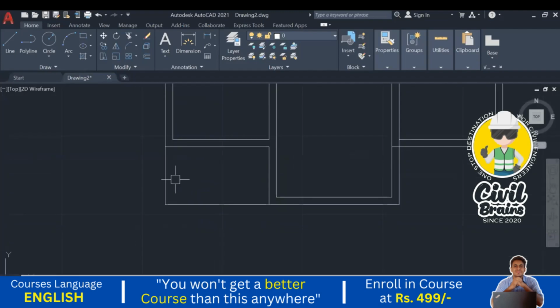Just come here. How to draw that? What is the width of the steps? The width of the steps has the tread and the riser. In the steps there are two parts, the tread and the riser. If you see from the top, you will see the treads, and if you see in the elevation, you will see the risers. Always remember this, don't get confused in the steps. So we are seeing from the top, then treads. How much are we going to consider? Treads we are going to consider as 0.3 or 300 mm, and risers we are considering as 150 mm. Okay, this is the standard as per the IS code.